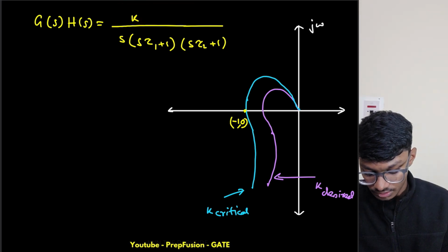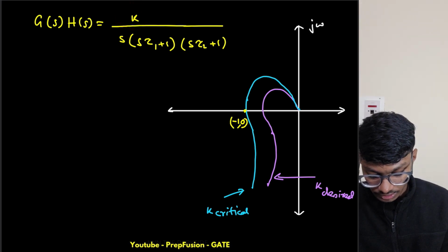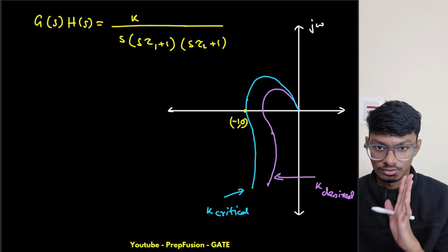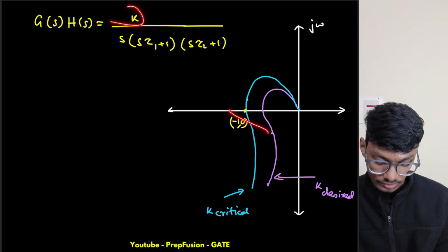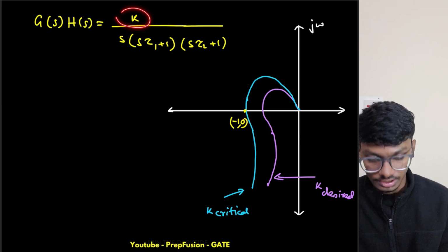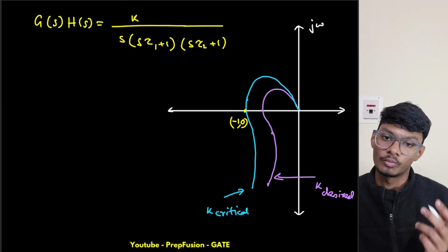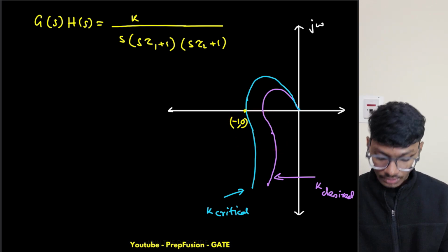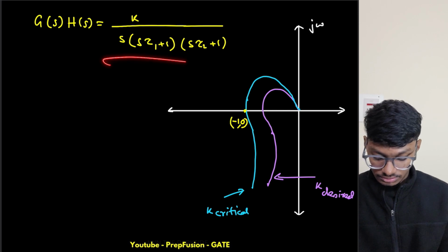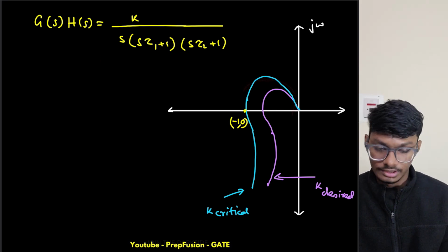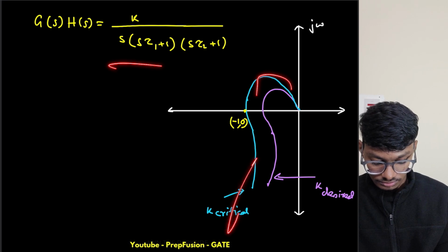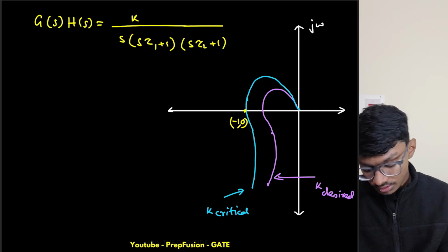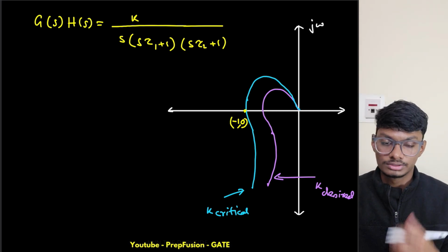All this is fine. The main gain depends on k itself. If I multiply k, this will be expanded or contracted. Gain varies with k. Obviously if I vary omega, that will vary, but if I keep my omega constant and vary k, gain will vary with k. This is an order 3 system, starting from minus 90 and ending at minus 270 degrees. So this is this one.